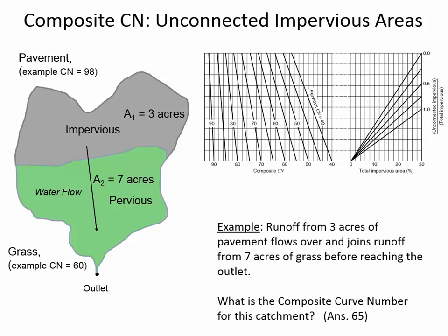And so all of that runoff, if they didn't put in storm drains, and they have, but if all of that runoff was going over the surface, that would probably generate less runoff in the stream than if that call center was at the bottom right next to the stream, because that's impervious area with runoff going over the surface. But as it ends up, it's so steep near there that it wouldn't do a lot of infiltration just because of how steep it is.